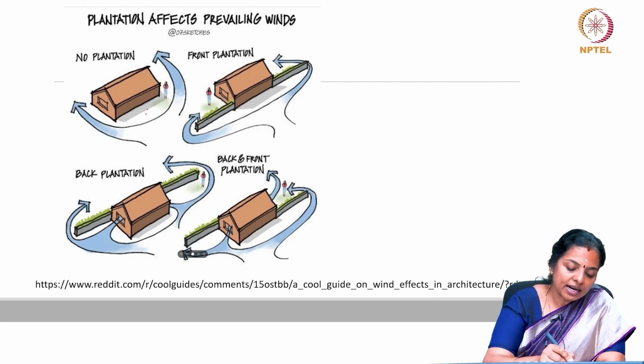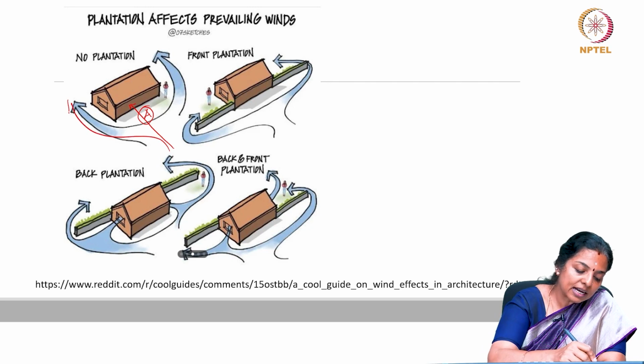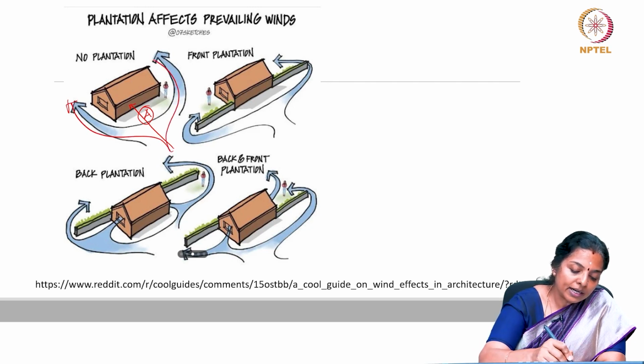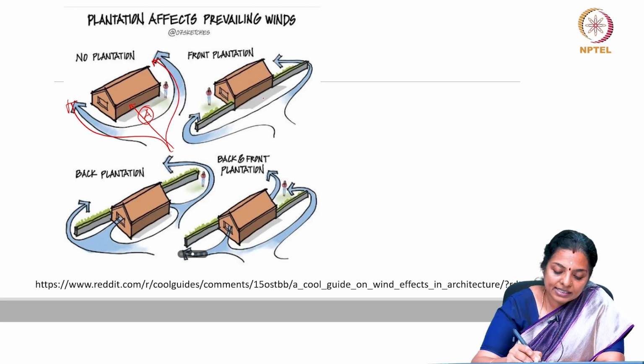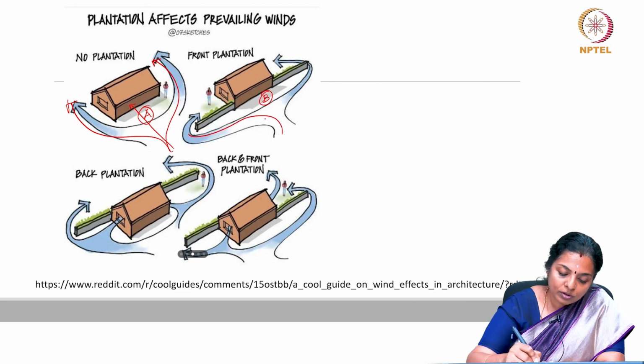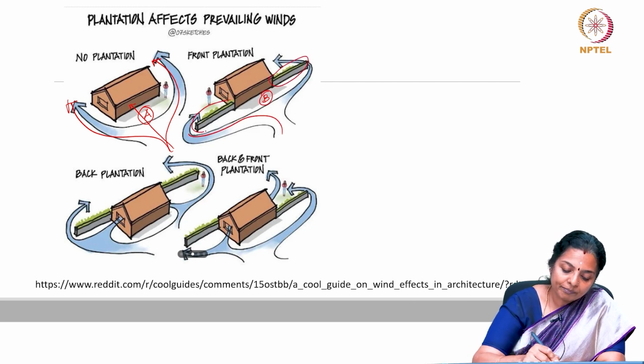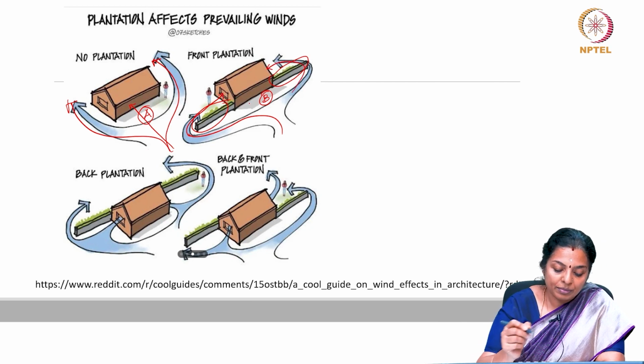In a situation as A, there are no openings along the direction of the wind, and the house acts as an element to divert the breeze out. In the second scenario B, the wind is diverted out, but here you have two elements which divert the breeze in, and because of this the house will be ventilated.